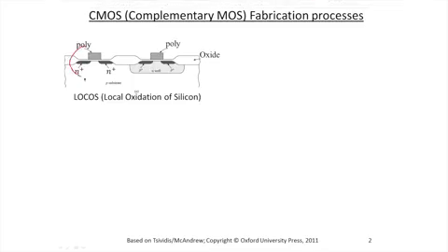You see here the N-channel device, which we have already discussed. And here you see the P-channel device. Just like the N-channel device has a P-type substrate, the P-channel device has an N-type substrate called the well. This is an N-type well. The source and drain are made of P-type material, and when there is enough negative charge on the gate, then underneath it, it attracts holes, and the holes form a bridge between source and drain.